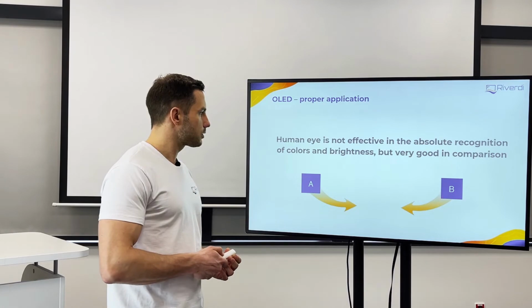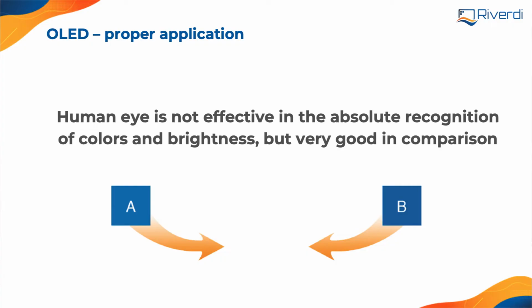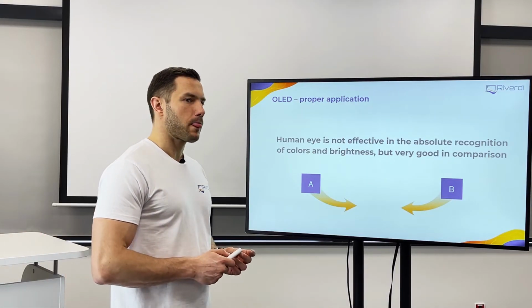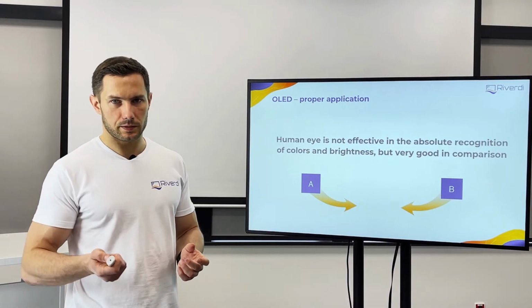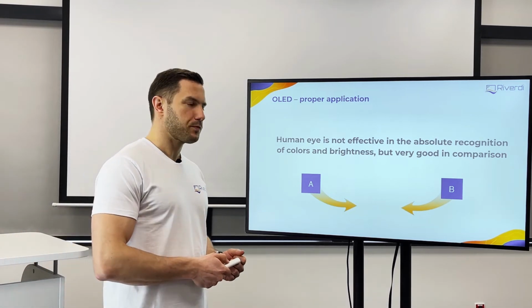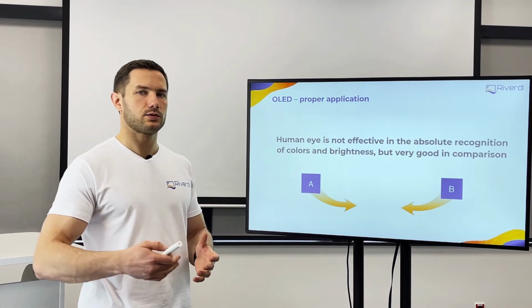Let's talk about the adoption of OLED displays, because with a TFT, again, I will repeat, we have a backlight. So if the backlight decreases in brightness, the whole display decreases in brightness. But here every pixel is a backlight itself, it's emitting light. So if we have a lot of display pixels next to each other, and we use them, the brightness decreases according to use time.